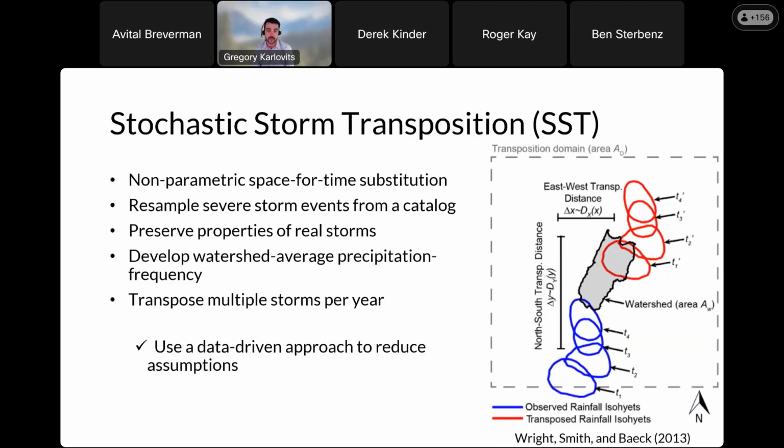properties. What this does is that it avoids having to make any assumptions about how the rainfall occurs in time and space, what its frequency is, because that whole slippery question of what's the 100-year storm really causes modeling issues. When you call it a 100-year storm, what specific property of it has a 1% ACE? Is it the point maximum? Is it an area average? What duration are you measuring that over? And then you have to answer questions about what about the temporal pattern? What about the spatial pattern?